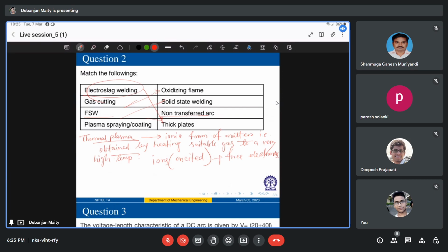However, the basic requirement for such activity is a constricted jet of high temperature plasma flowing at a high velocity, right? And in order to artificially generate plasma, a plasma forming gas like air, hydrogen, argon or nitrogen can be introduced into a gas chamber at some flow rate, and this gas chamber contains a tungsten electrode which is connected with a negative terminal. So these are some equipment or principles in terms of how you can produce this plasma.